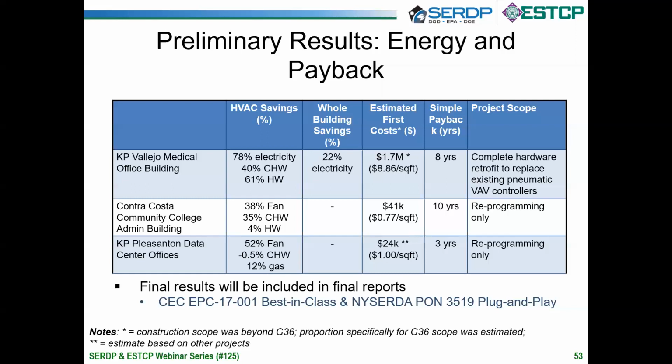On the Contra Costa Community College admin building, the new sequence of operation had an optimal start logic, which basically means the control system learns when it should turn the building on to be comfortable at the beginning of occupancy.